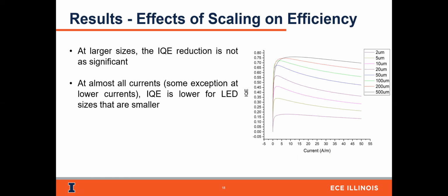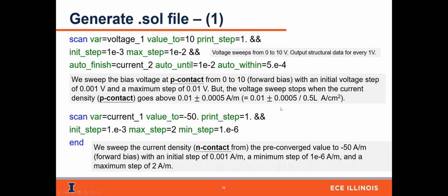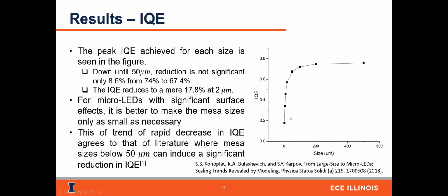You use the PLT file or you use CrossLight view to extract the IV curve and then collect the peak IQE so that you can plot this kind of data. You need post-processing techniques to plot this data, either using Origin Lab or using Excel.